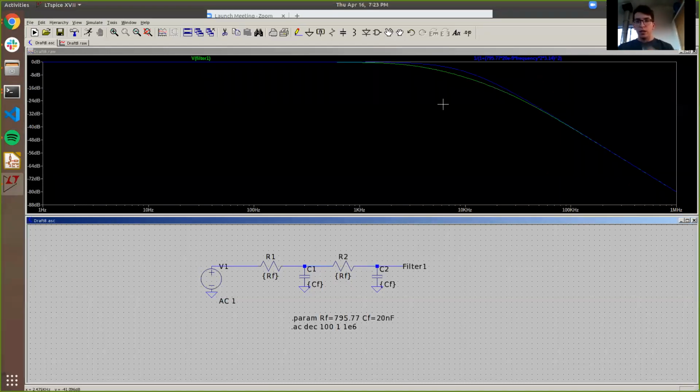Cool. So that's interesting. They're a little off. You can see that the green line here stands for the Bode plot of the filter, and the blue line here stands for the theoretical response that you should have seen. There's a bit of a difference, and I think that's exactly what Brian's story was trying to get you to see: that 2 filters in a row placed together like that causes them to couple each other. Coupling each other just means that one system is affecting the other system in an unexpected way.